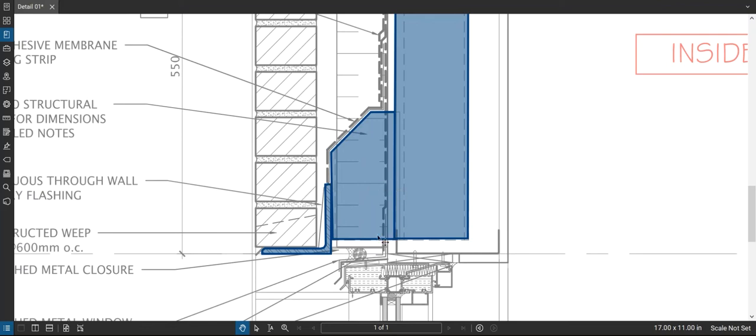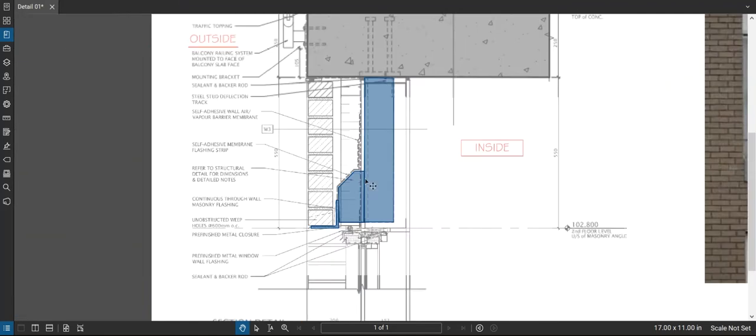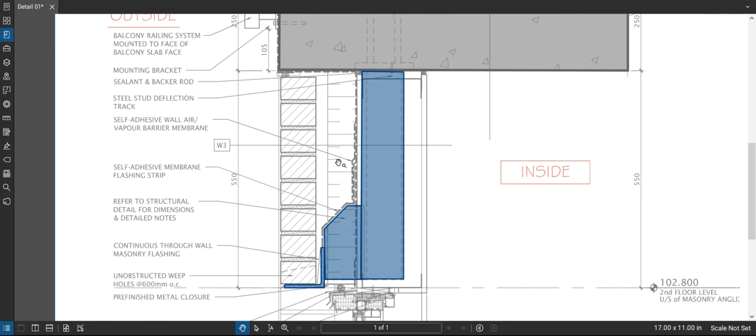It could have just been a rectangle piece in here. They've taken it taller and put an angle on it, and it looks like they've done that so that the flashing can go over top of it and give a shape or form for the flashing, basically. But anyways, that would be the secondary structure there, which is all that's needed just to support that brick. I guess I should say it just supports the brick.